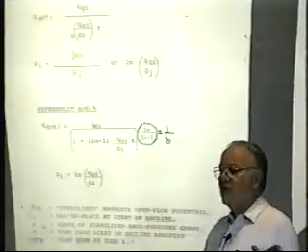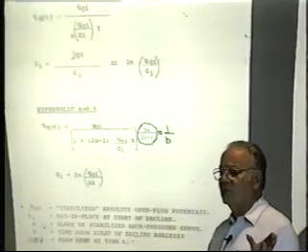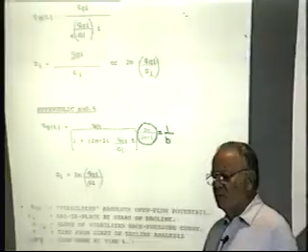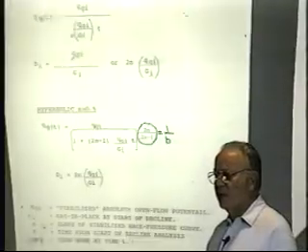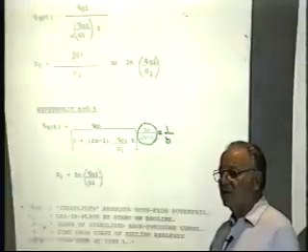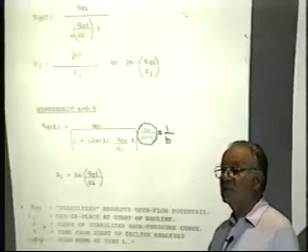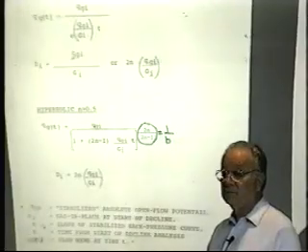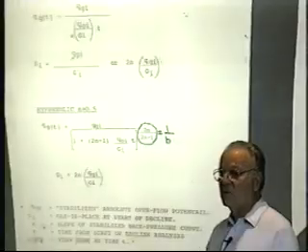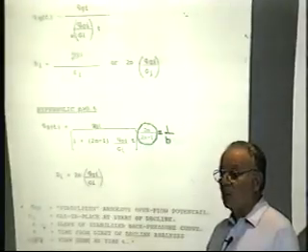All the years that I was working, I used to wonder why the gas in place I'd get from material balance, P over Z plot versus Cume, was always so much lower than the gas in place the geologists were furnishing us. But when you start understanding layered no cross flow, you find out that the gas was there. We just couldn't see it. And I'll go over an example later of the Ghost River in Canada, where it's exactly the case. All the gas was there.